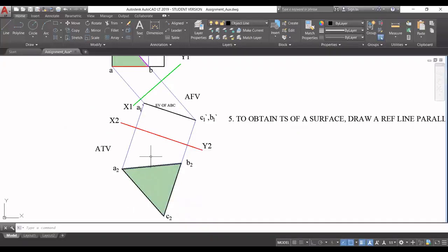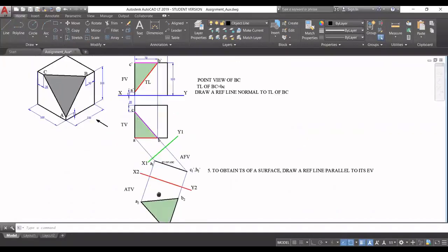Another important takeaway from today's discussion is that whenever you are dealing with such problems in auxiliary, you always take care of the two consecutive lines. Whenever you consider any two consecutive lines, like the pair of consecutive lines is in this case either xy and x1y1, or x1y1 and x2y2, whatever may be the case, if you are dealing with a pair of consecutive reference lines, then the distances of all the points lying on the outer zones of both the consecutive reference lines is the same.